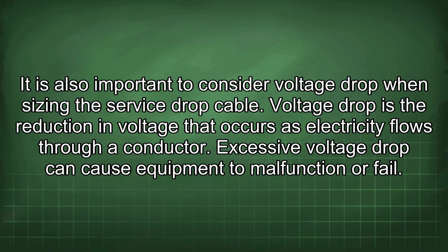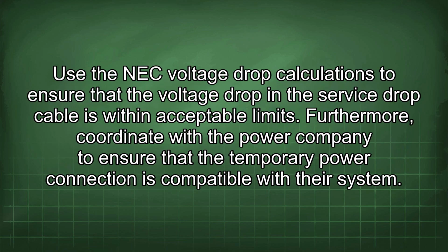It is also important to consider voltage drop when sizing the service drop cable. Voltage drop is the reduction in voltage that occurs as electricity flows through a conductor. Excessive voltage drop can cause equipment to malfunction or fail. Use the NEC voltage drop calculations to ensure that the voltage drop in the service drop cable is within acceptable limits. Furthermore, coordinate with the power company to ensure that the temporary power connection is compatible with this system.